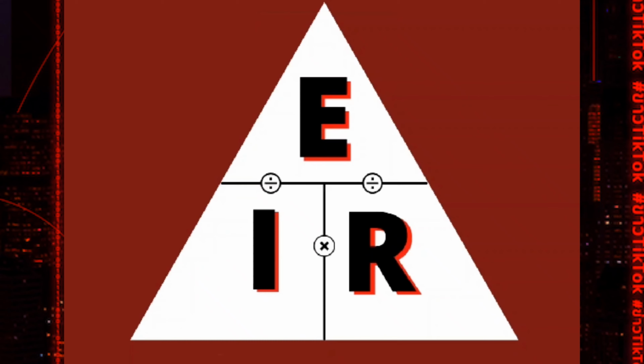Another way to familiarize yourself with the formula is to remember the Ohm's law triangle. If you want to solve for I, which is the current, just put your thumb on the letter I, and as you can see, E is over the R. So just write E divided by R.